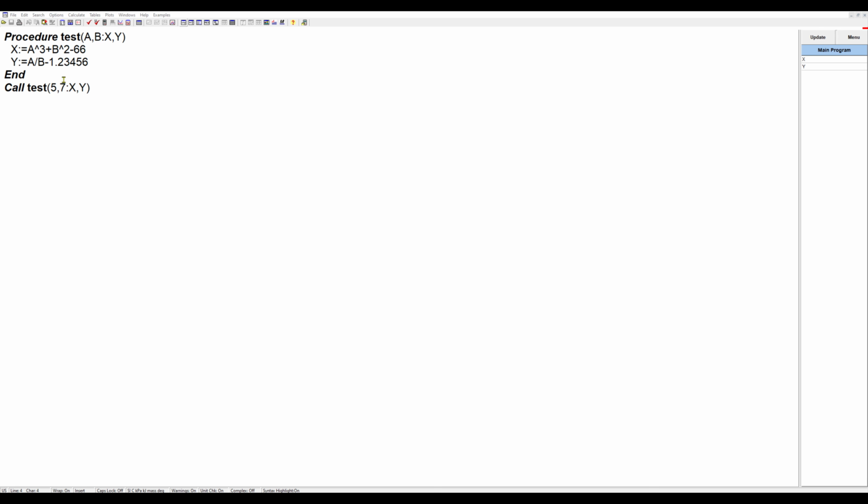Last but not least, which is a very important part here, we can actually give the outputs here in this Call statement, and then EES can calculate the inputs based on this equation. For example, if I put here A and B as our inputs and give here, for example, 0 and 0, so these equations are both equal to 0.